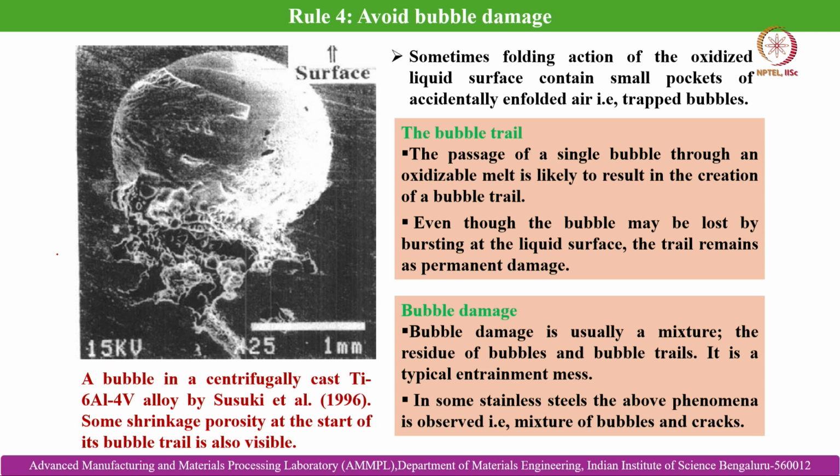cores. And during melt pouring within the mold cavity, we are using some binders or additives within the sand to bind it, and also we are using binders and additives in the core. That can undergo evaporation because of the heat imparted by the liquid melt, and that can cause gas evolution.